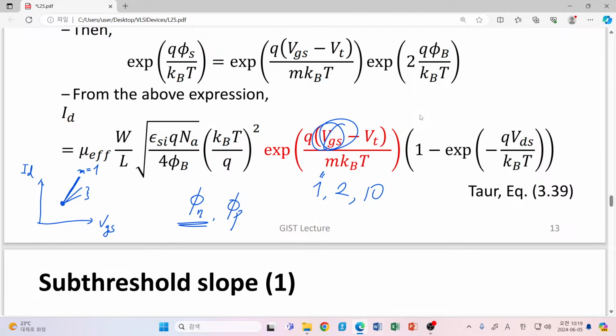So in this course, you should be able to identify your current density in terms of this quasi-Fermi potential. The gradient of quasi-Fermi potential is related to your Jn expression and Jp expression. In my opinion, that is the key point. This is a long story, so we could not cover it in our junior level semiconductor physics or device course, but in this course we spent quite a long time on this concept.